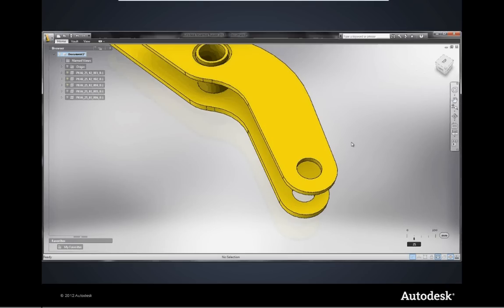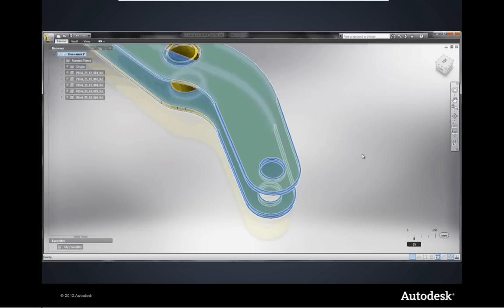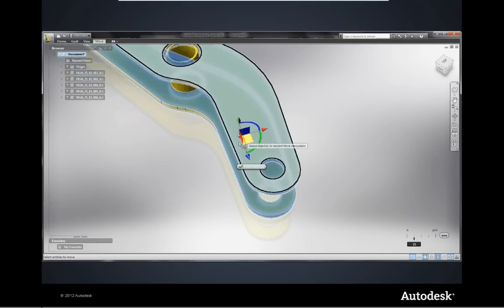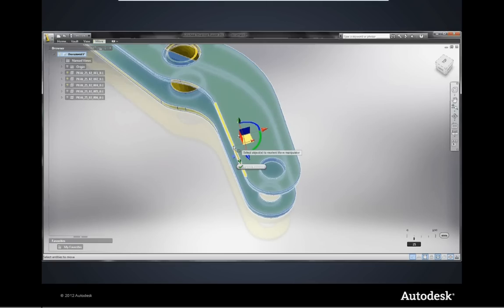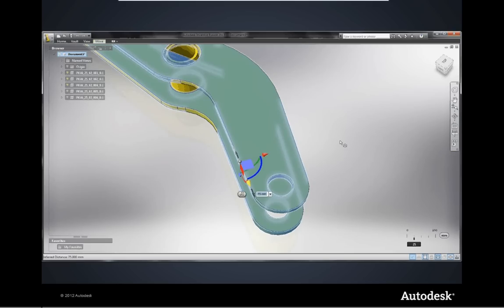Fusion also lets you take an Inventor model and push and pull that model to create surfaces. So if you ever want to do an organic surface model, then you can literally start off in a block in Inventor, push it through to Fusion, and then push and pull the edges of that model to actually produce an organic surface model, and then push it back to Inventor again. This can be done with mirror planes on as well, so as you edit one side, the other side is changed as well. Here in this example, we're actually stretching a part of our assembly, just using the stretch tools within Fusion and extruding that or stretching that by a known value.